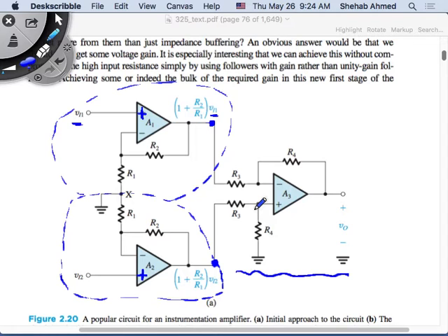The advantage over the previous circuit versus this circuit is now I can have my gain stage here in the non-inverting amplifier section, the front end, right? And then I make this low gain but high input impedance, without actually paying too much. I don't lose on my R input. So my problem with this previous circuit was two problems. And one of them still persists in this configuration, and I will solve it in the next configuration. People, we keep solving problems here.